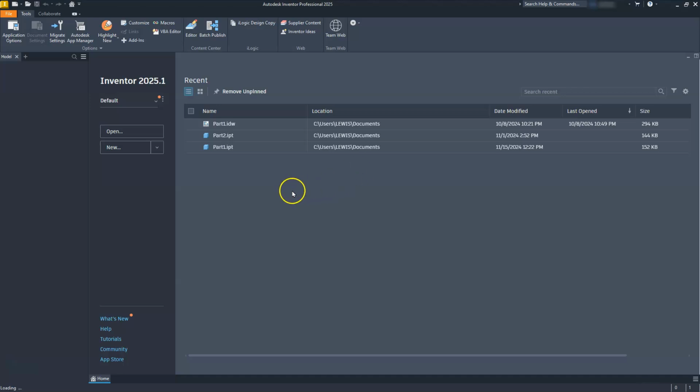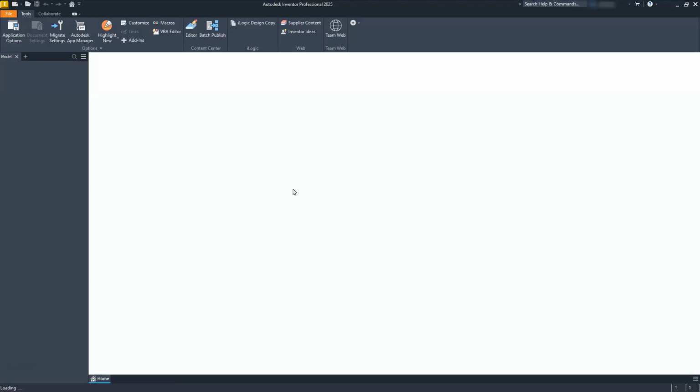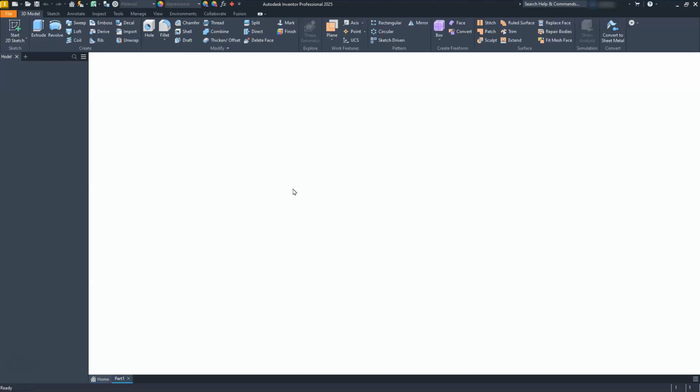But as this loads up, just be thinking in your mind what we need to create, right? So we need to deal with a 3D sketch. 3D sketches are different than the 2D sketches. Remember, we're going to deal with all three planes at once. But we still have to locate where the origin is. Now, you don't have to locate that immediately in the beginning, but you're going to have to do it, or what I like to do before I get out of the sketch, because that's going to help me when I go to create the profile that I need to sweep.